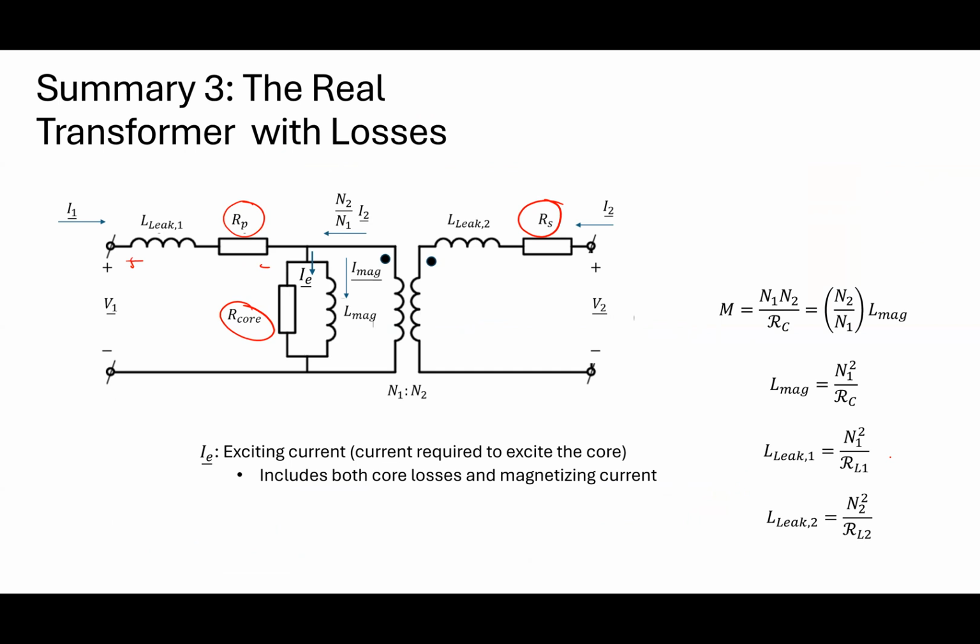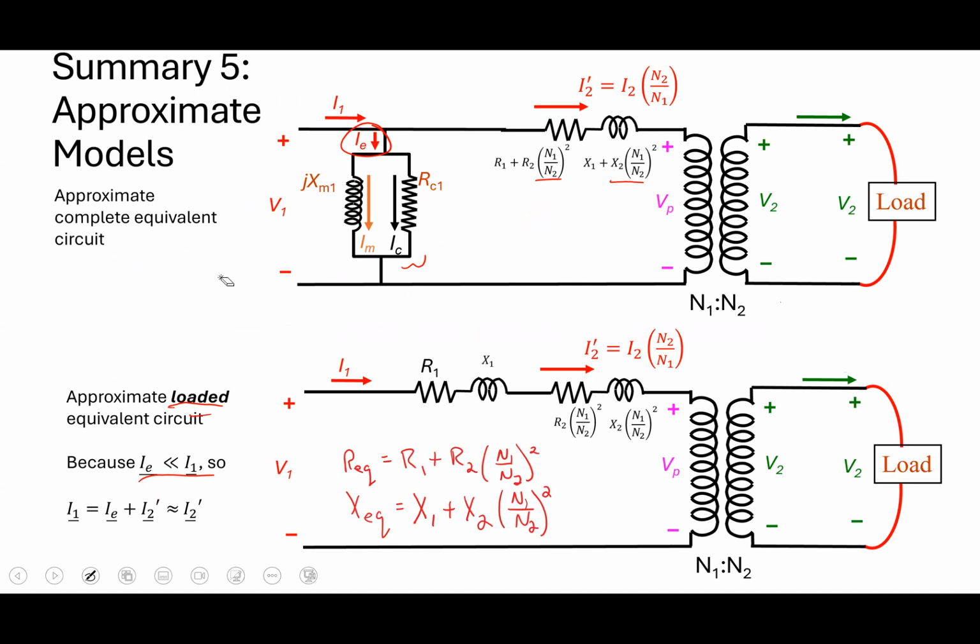Under load, which impedances mattered? Which ones do we say mattered under load? The leakage ones, and these resistances in series. The current through here should be really small because these impedances are really big. What they're telling me is basically the values here in this model under load.